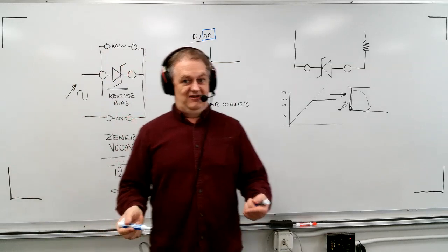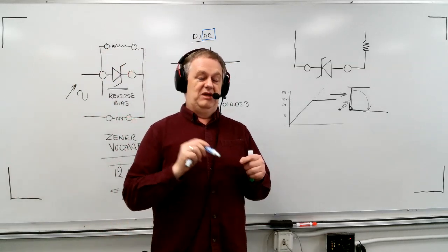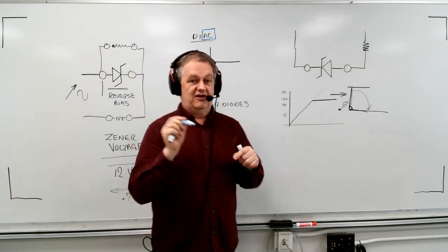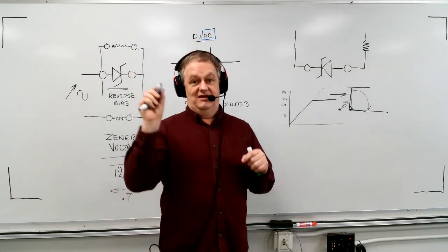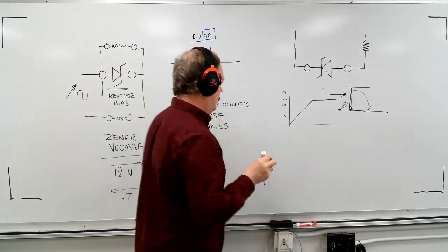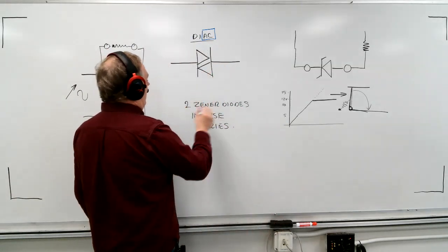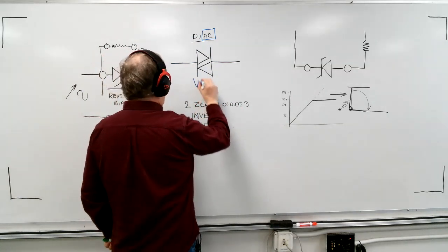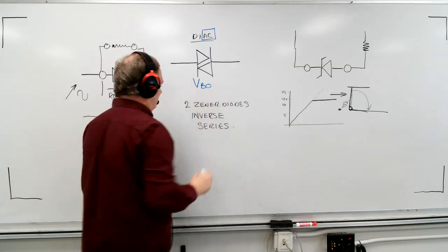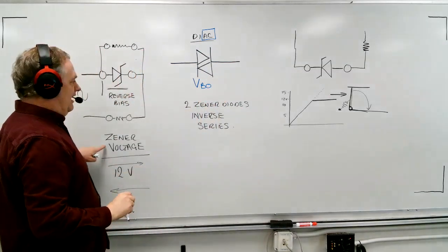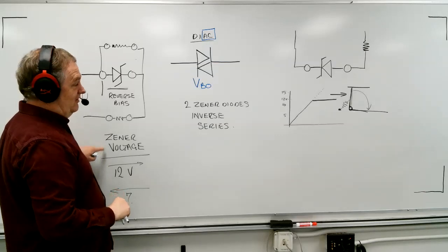The triac is an AC device, and we know current has to be able to go in and out of the gate, and so the diac has to be an AC device to let current in and out at a specific point in time. And when is it going to do that? Well, when it reaches its voltage breakover, which is exactly the same. It's a different name, but it means the same thing as Zener voltage means in the Zener diode.